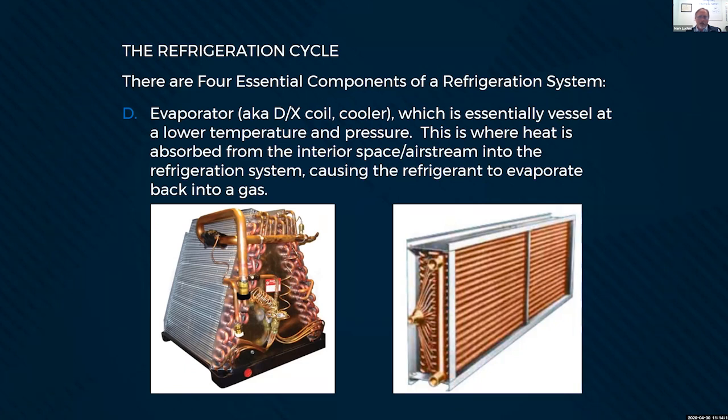And you can see here the distributor where the refrigerant comes in as a very fine mist in these small tubes. And as it expands and evaporates, the tubes get larger until it's collected in a header and brought back to the compressor.